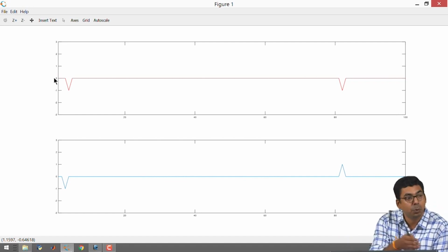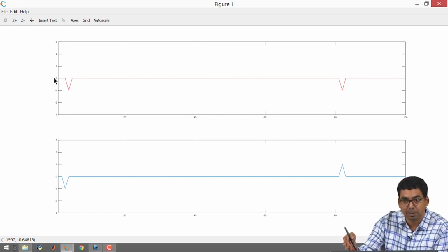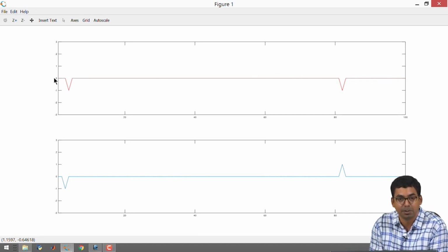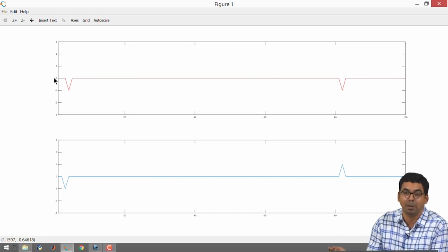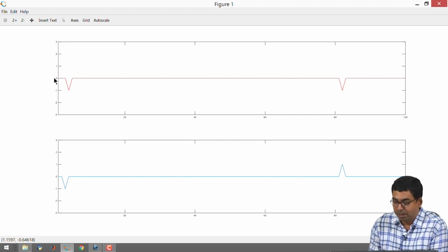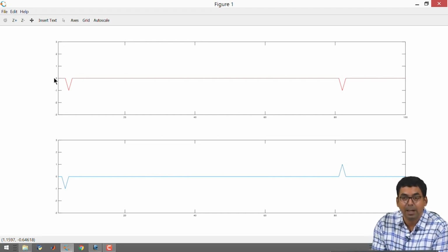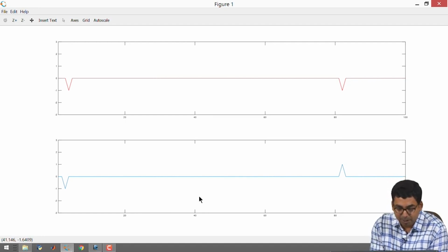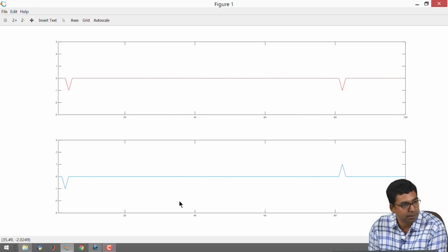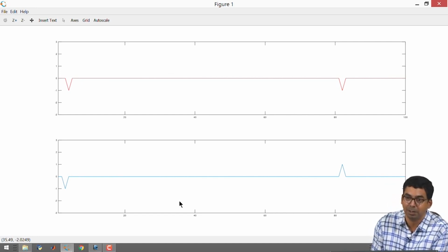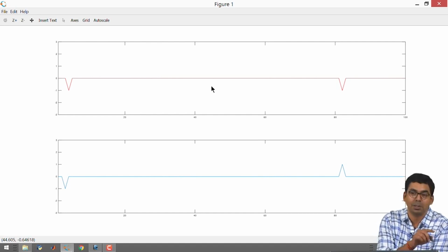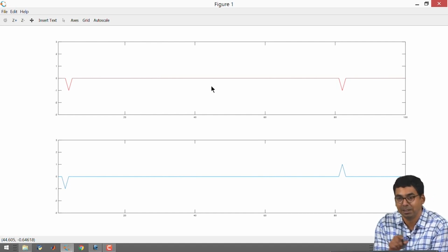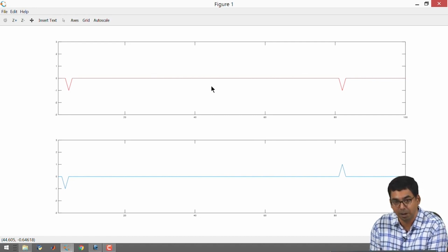Remember that we had two different boundary conditions for simulating this particular section of the transmission line. On the left hand side we imposed one condition, and on the right hand side we imposed the opposite condition. This also has an impact on the way the current flips back and forth. Correspondingly one can calculate current reflection coefficients, but you can derive the current reflection coefficient from the voltage reflection coefficient, because you can apply Ohm's law and also the sign changes for your forward and backward currents, and you will be able to figure out what's going on.